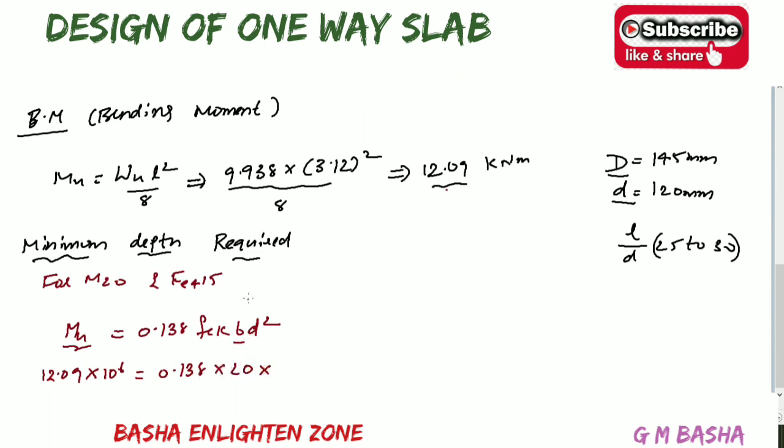How much is b? We are considering everything for 1 meter only, so here I am taking 1000 in terms of mm, and d square. If you simplify this, you will get the d value. That d value will be exactly in the range of 66 to 67. So the minimum depth required for this slab will be this much. We provided 120 mm, while the minimum depth required for this slab is 66.2 mm.